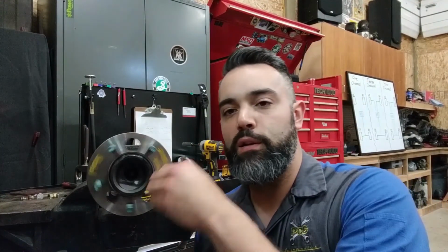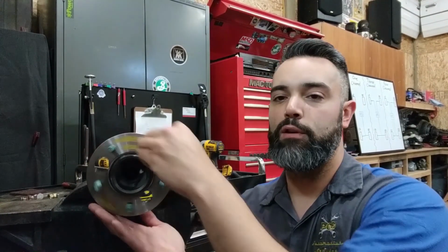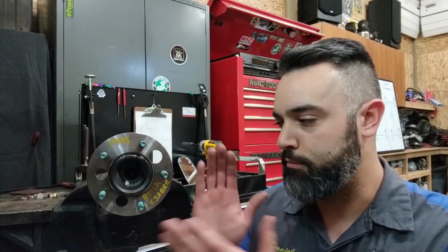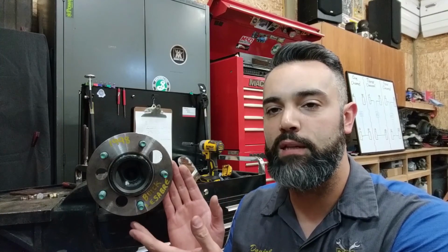So as the wheel is turning and it approaches a slip, so eventually it's going to stop, the signal to the computer shows that that wheel speed sensor is not producing a signal when it is stopped. If it sees other ones producing a signal, then the computer can determine that this brake needs to be released in order for this wheel to keep spinning and maintain directional stability.